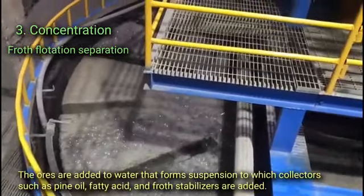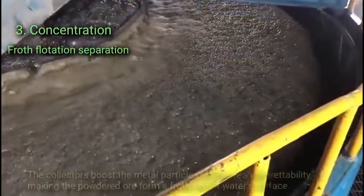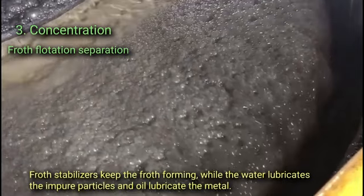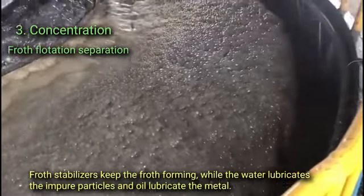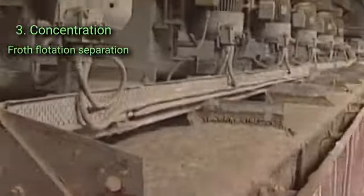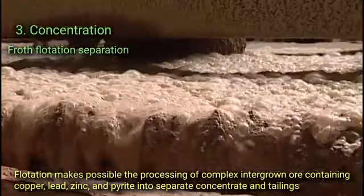The ores are added to water that forms suspension, to which collectors such as pine oil, fatty acid, and froth stabilizers are added. The collectors boost the metal particles of the ore's non-wettability, making the powdered ore form a froth on the water surface. Froth stabilizers keep the froth forming, while the water lubricates the impure particles and oil lubricates the metal. The suspension needs to be constantly stirred with the help of agitators for the froth to keep forming. Flotation makes possible the processing of complex intergrown ores containing copper, lead, zinc, and pyrite into separate concentrate and tailings.